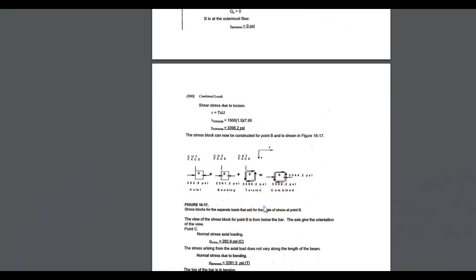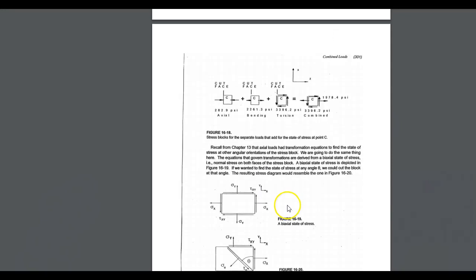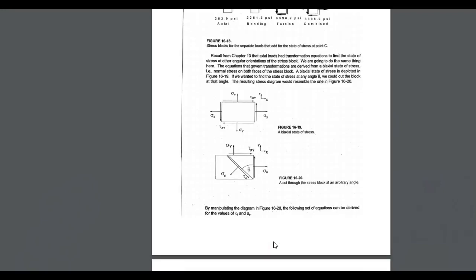Now remember, we can't really use a torque if we have a rectangular cross-section, because we need that extraordinarily high degree of symmetry in order for our equations to work. So that's not going to be a concern, but could we possibly have a circular shaft that also has not just a tau from a torque, but a tau from a vertical load as well? I think that will be for discussion for our final lecture on this chapter.